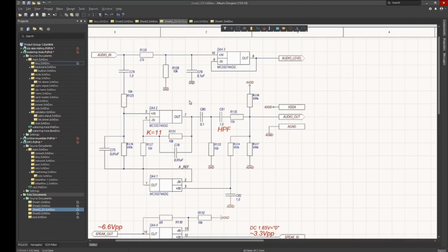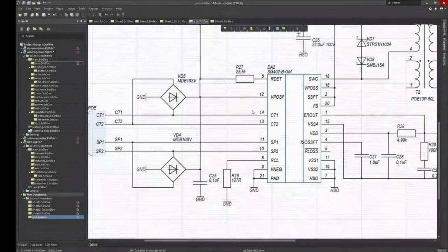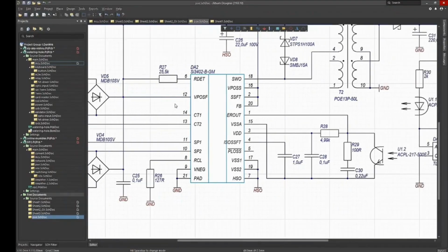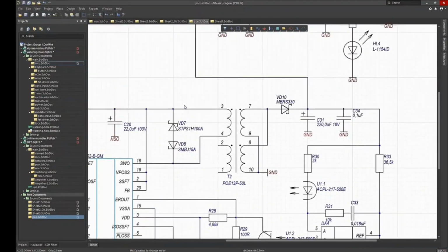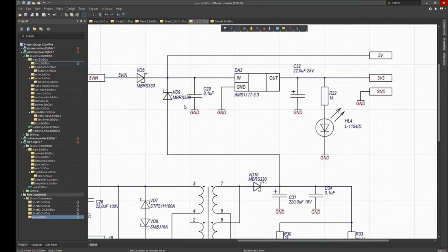The fourth mistake is reading the schematic as a picture, not as a flow of energy. Current always flows from the source through the load to ground. If you do not understand this, do not imagine how currents move in your circuit, then you will never understand why there is a diode here, a diode there, why capacitors are placed here, and so on.